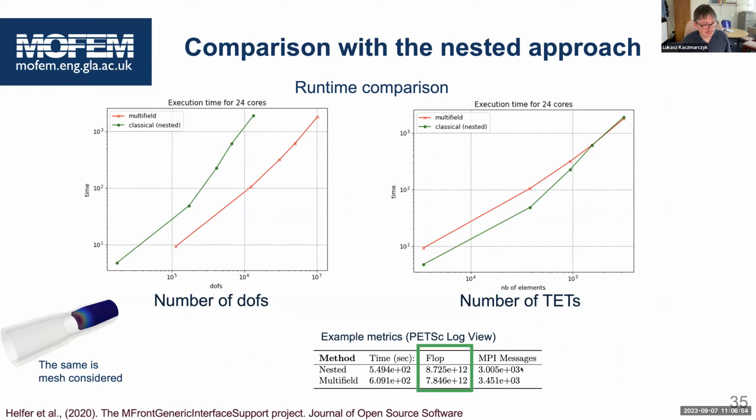Moreover, the formulation which you will have in the notebooks allows you to run both hex and tet meshes. You are free to choose the mesh, and it allows you to run 2D and 3D problems. The same code runs 2D, 3D, hex, tet, quad, and triangle meshes. In 2D, you can mix the triangles. You can make heterogeneous meshes, mixing triangles with quads.